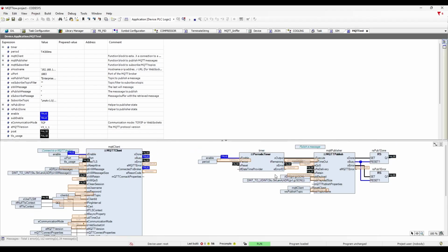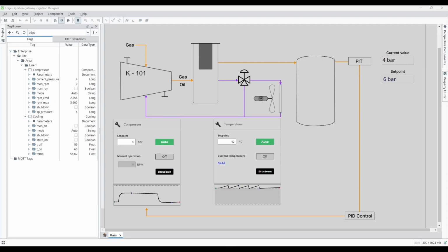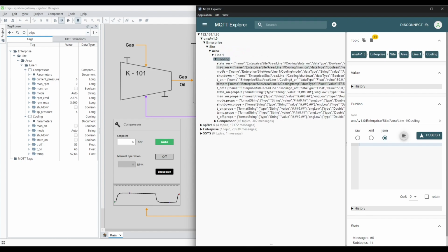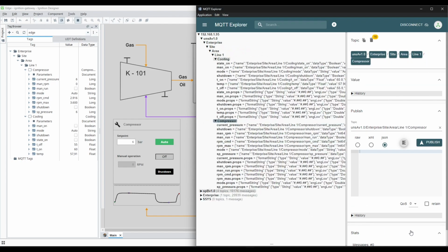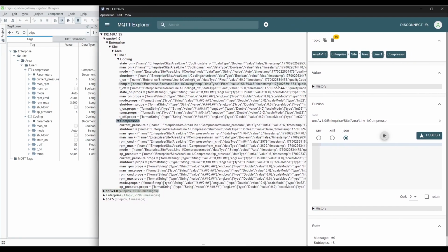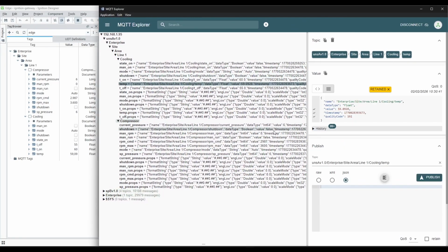On the transmission side, we can see how data is sent back to the broker by both configured transmitters. This data could be sent back to CodeSys and used by another custom program to write back to source variables. However, this functionality must be explicitly designed and implemented, as the MQTT protocol does not provide direct variable-level control. This distinction is intentional and reflects the design goals of MQTT as a protocol.